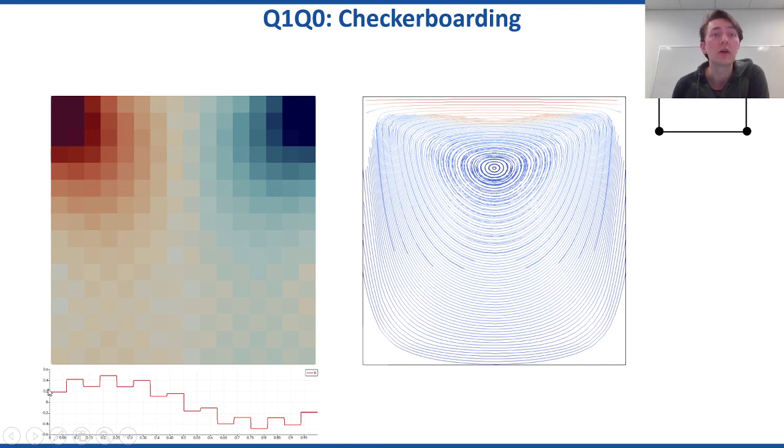And we actually find that this is precisely showing what we just pointed out. We get this true solution of our pressure, the one that we want to obtain, but it is overlaid with this funny looking up and down jump. So it's going up and down, up and down, up and down. That's precisely that checkerboard pattern that is overlaid on top of the true pressure solution.